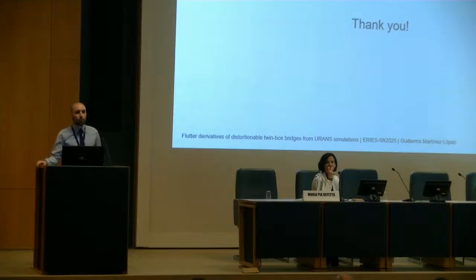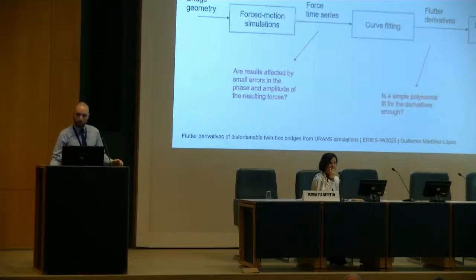So yeah, we used a forced motion approach. That means it's not free vibration. That means that I'm imposing a sinusoidal motion on each of these displacements, each of these degrees of freedom. So in my simulation, I'm modifying the geometry, I'm modifying the mesh, but it's not an FSI simulation. I'm not solving the structure at all. I'm just imposing a prescribed motion. The springs don't matter for the CFD. I just have the sinusoidal motion, I extract the derivatives, and the stiffness of the springs comes later. When you do the solution of the flutter equations, of course, there you need to consider the stiffness of the springs.